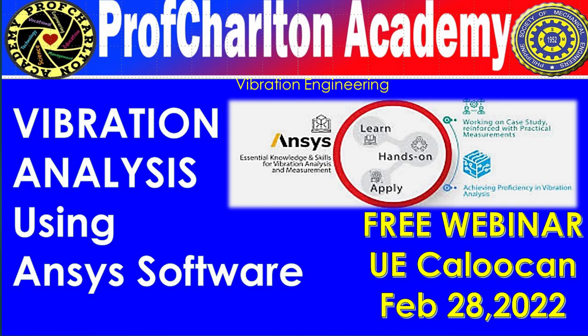So in ANSYS, we have a simulation-based solution. This solution allows you to check whether the particular part that you have can be printed or not. It will also tell you what the deformations will be if you print this particular shape, or what the distortions or warpage will be. So this is the purpose of the additive manufacturing simulation solution.